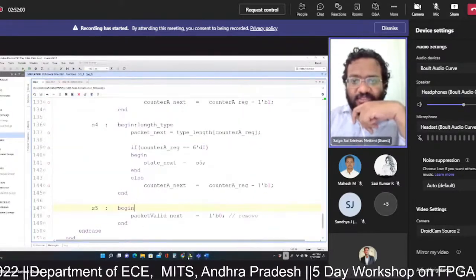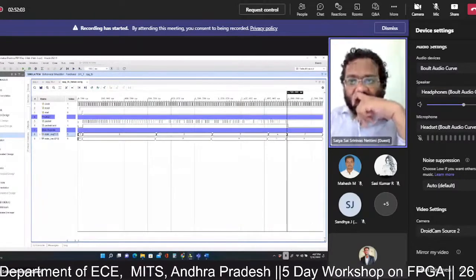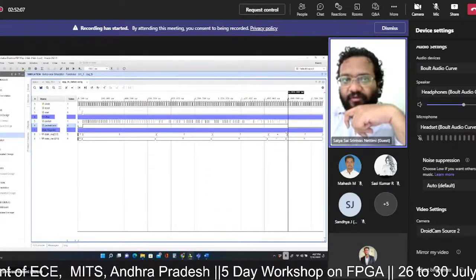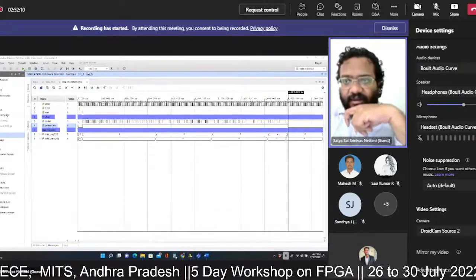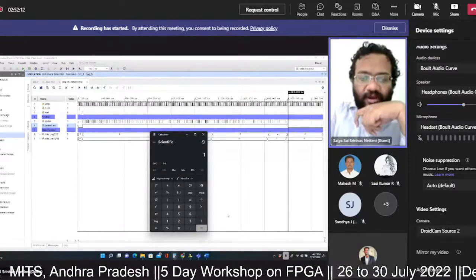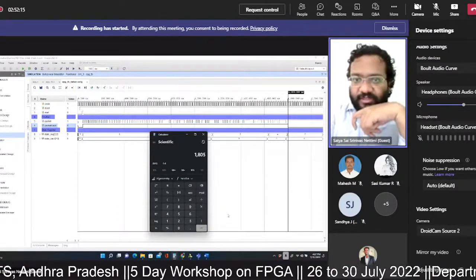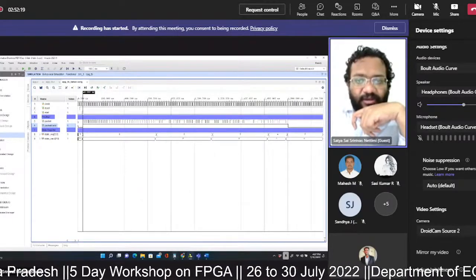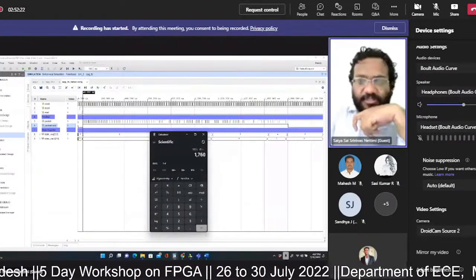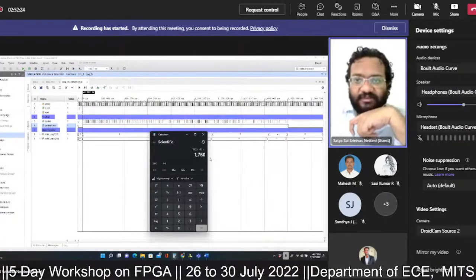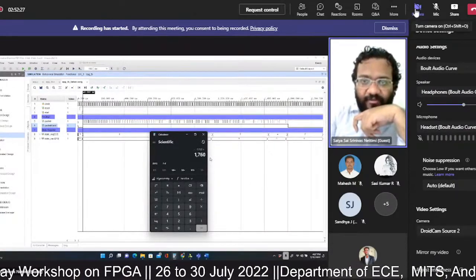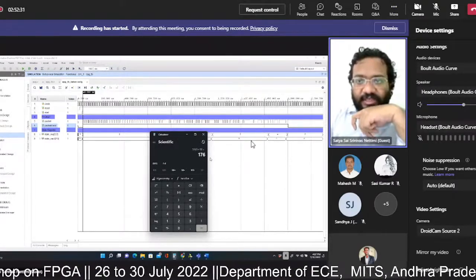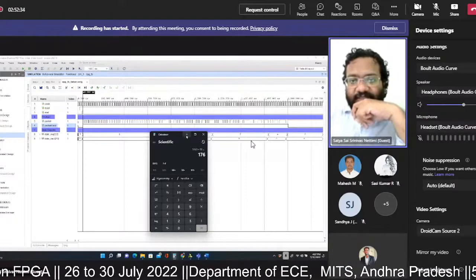We will check whether the sequence is coming as appropriate or not. The frame ended at a timestamp of 1805 nanoseconds, and the frame began at a timestamp of 45 nanoseconds. The resultant is 1760 nanoseconds. If we divide it by the clock time period, that is 10 nanoseconds, we have 176.